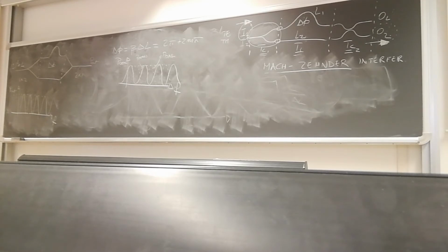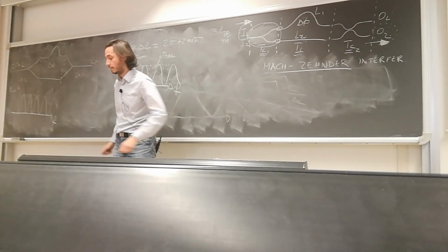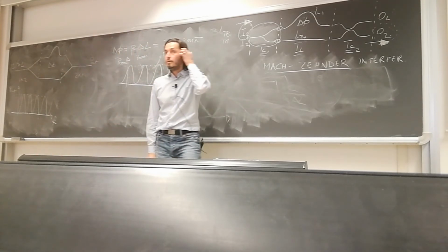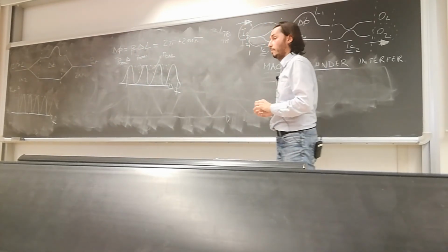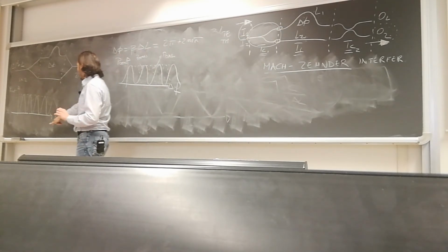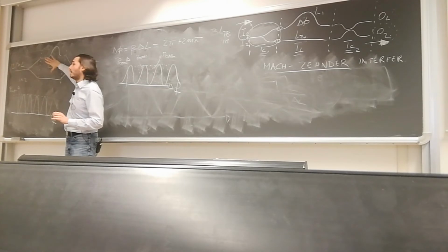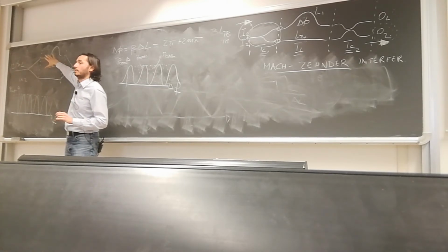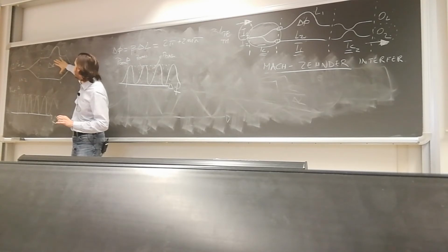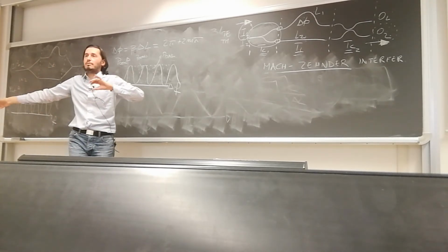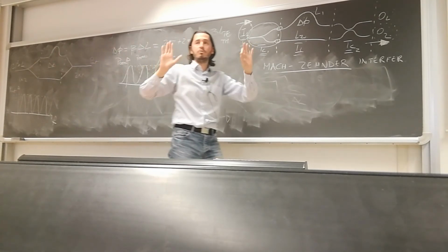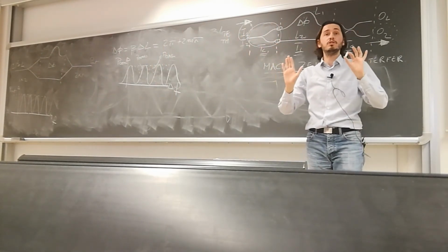This is for a Mach-Zehnder with a coupler. Again, without making any calculation, physically, because here you have both cross and bar, and you have cross and bar. But in this one, just one. Thank you. When I change the frequency, I change the relative phase. I change the relative phase of the light arriving at the input port of the Y branch. Does it matter or not? The relative phase at the input of a Y branch. Of course it matters.